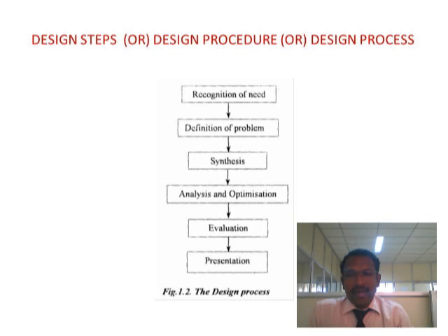Then analysis. Analysis means you have to find out the forces acting on the component by using strength of materials concepts, engineering mechanics concepts, etc. So after that we have to select the suitable material for the particular application. Then after analyzing these things, you have to fix the dimensions for the component.